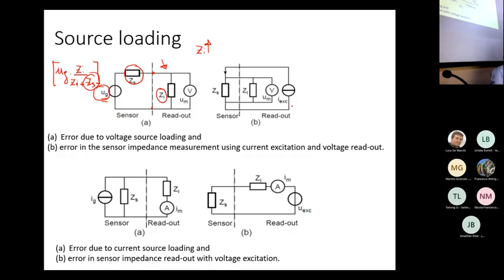But we may have also a different situation in which it is the impedance value which is used to sense a given physical quantity. So the physical quantity is measured by analyzing the variations of the sensor impedance. There are many sensors whose working principle is this one, for example, strain gauges.